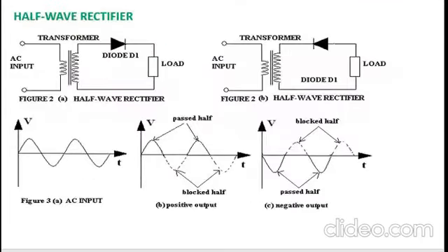And the rectifier, as we have seen in the other class, is of 2 types. We have what we call the half-wave rectifier, which allows only one part of the alternating signal to pass and cuts the other part. If you connect your diode like this, that is anode in contact with the transformer and the cathode at the other end, your AC input will now be only flowing in the positive direction. Anything below here, these dotted lines, means they have been cut. They cannot pass. So we maintain only this positive half, and that is why we call it a half-wave rectifier.